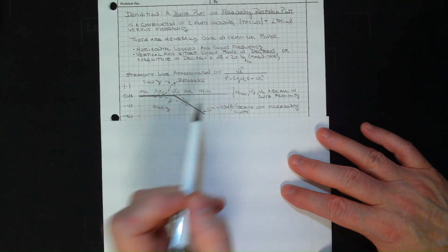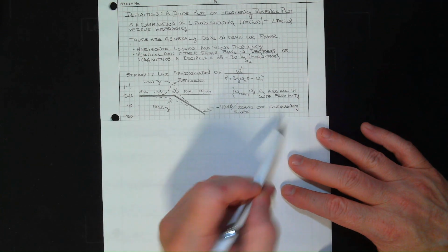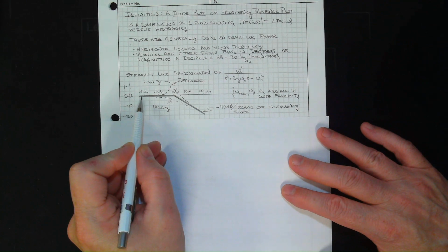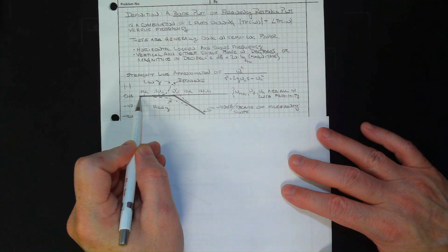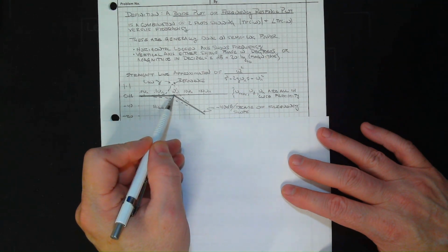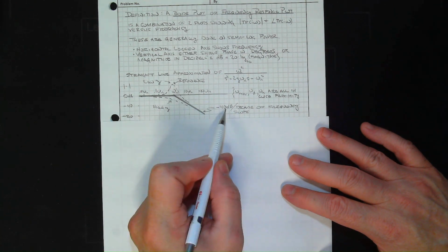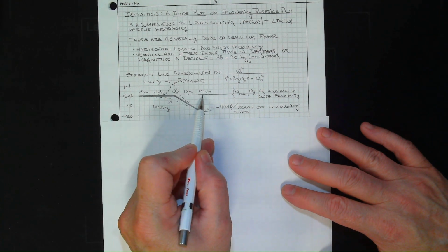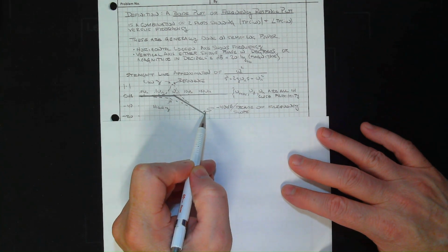So let's see what we have. I will note that omega d, omega max, omega n are all in close proximity as long as your damping is reasonably low. And so this is the straight line approximation. You go along, because at low frequency, it's going to be 1 or 0 dB. Okay. And then we go up to omega n, and from there, we drop at a rate of 40 decibels per decade. That's another way of saying a factor of 100.